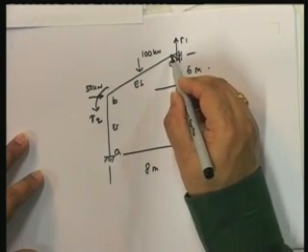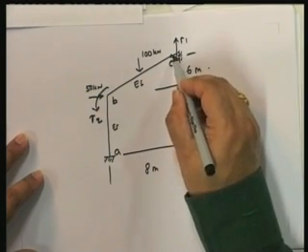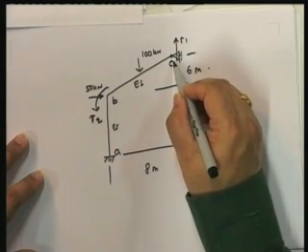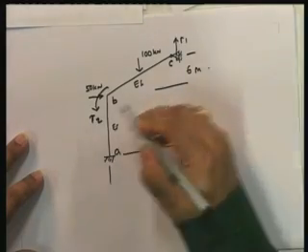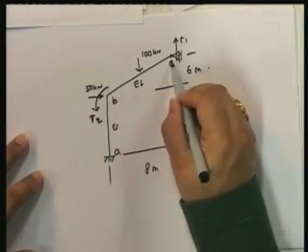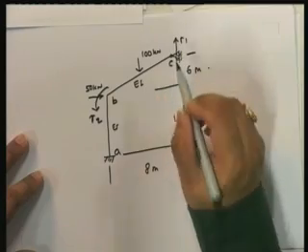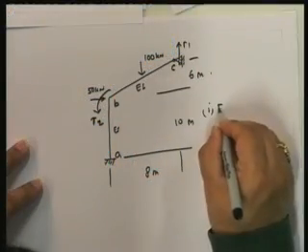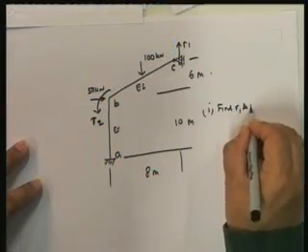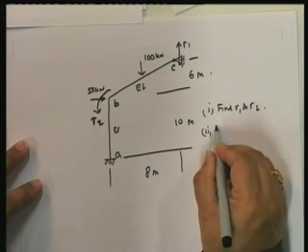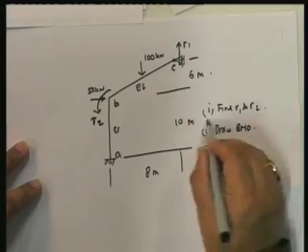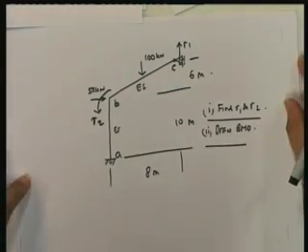Why? Actually in this particular case you have a third degree of freedom, but remember this is an end hinge, so I can actually treat BC as a modified member and keep AB as an original member. So BC is a modified member with a fixed end at this end and a roller at this end. Okay? So what I would like you to do is, given this problem, 1, find R1 and R2, 2, draw the bending moment diagram. Exactly the same problem as I have done.